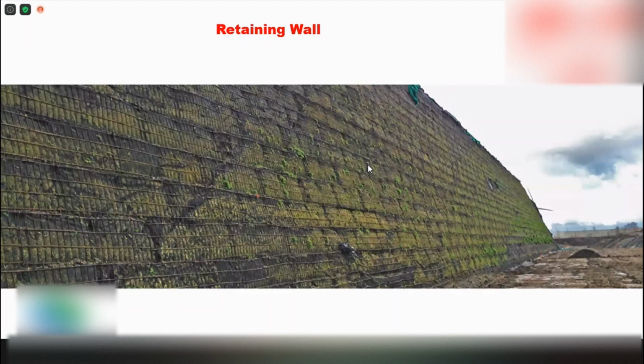Those are geogrid, and behind the geogrid there are geotextiles wrapped around to prevent soil from being lost through the roots. Those behind the geogrid actually come in bags, and you can build a very high wall. This wall is as high as 12 to 15 meters and almost vertical. The angle is more than 70 degrees, and we can actually make it vertical by having a facing material.